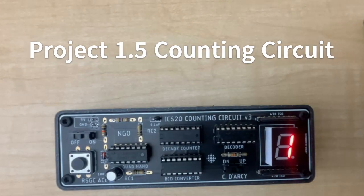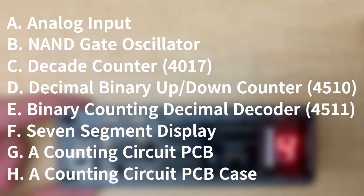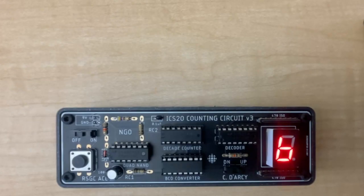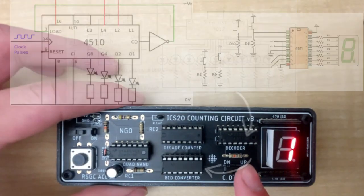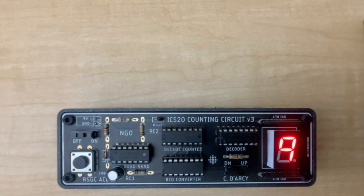Project 1.5, Counting Circuit. This project has 8 different subsections labeled A to H, leading up to the final counting circuit. A counting circuit is a circuit that counts up or down using clock pulses. It uses digital components such as a NAND gate oscillator, decade counter, binary decoders, and a 7-segment display. A counting circuit's main function is to precisely track the count number and show it in an easy-to-read format.